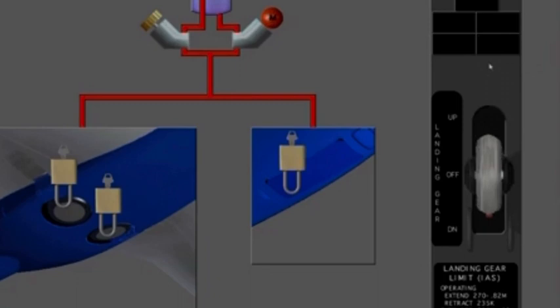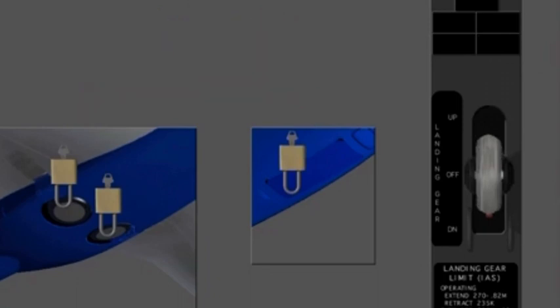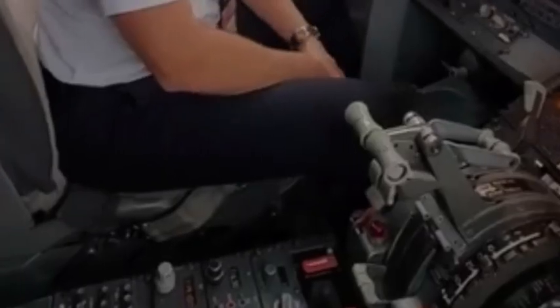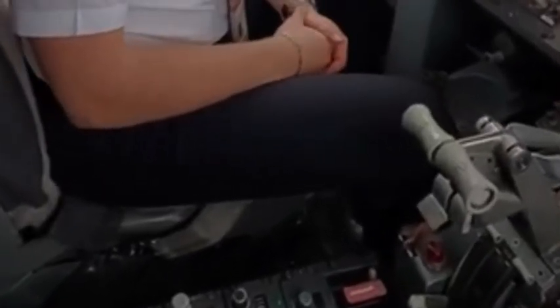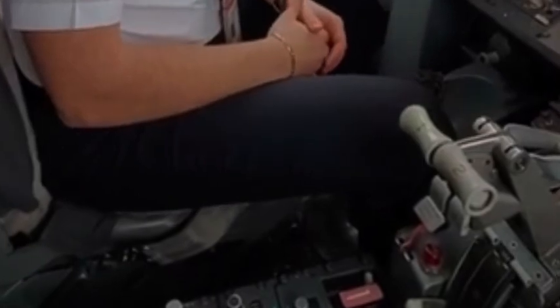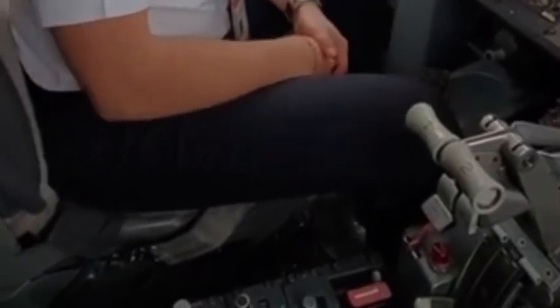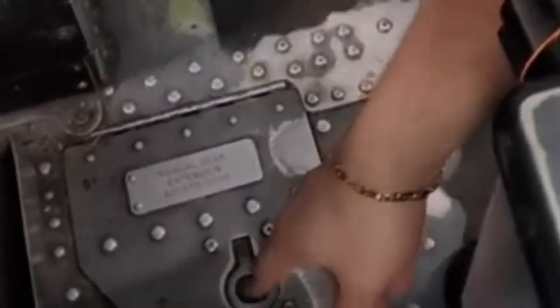During flight, if we lose hydraulic system A, we have a manual gear extension mechanism, same as we explained for the nose landing gear. Still on the panel at the back side of the first officer seat, the left lever is for the left main gear, and the right lever is for the right main gear. Pulling any lever up to the limit will unlock the uplock mechanism.